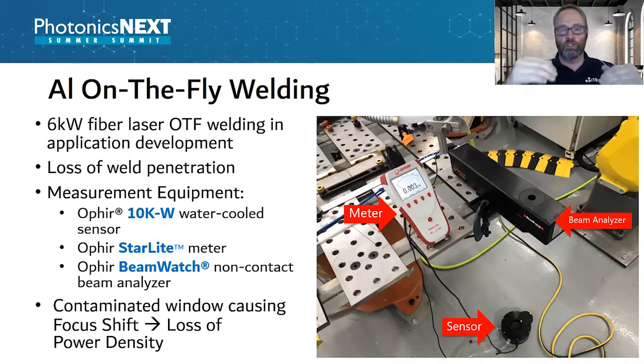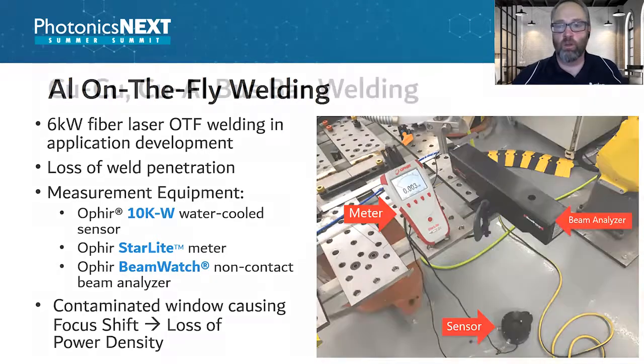If you think about what the laser is doing, it's focusing down to a spot, and if you have a drift of that focus spot, when you turn the laser on and as it goes up, what's happening at the work site? The beam size is increasing, right? So as the beam size increases, then you have a decrease of overall power density for the same amount of laser power. So obviously that's why there was a loss of penetration at the end of the weld.